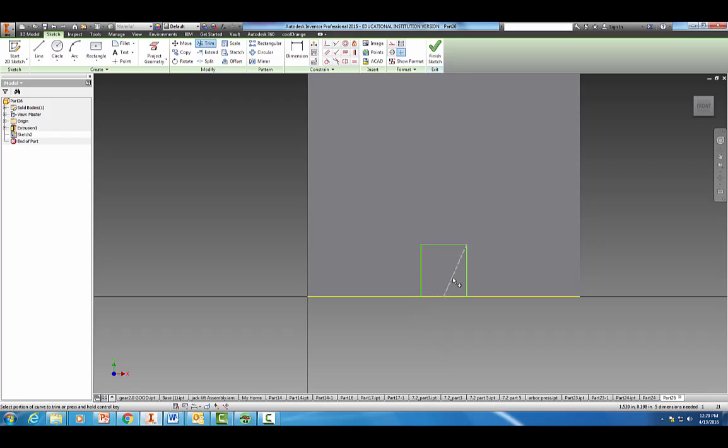Okay, and then I'm just going to trim it up real quick, before I add some dimensions here. So I've got to dimension this now from this edge, 0.5. And let's see here. It's 1.4 from the center. So here's what I'm going to do.